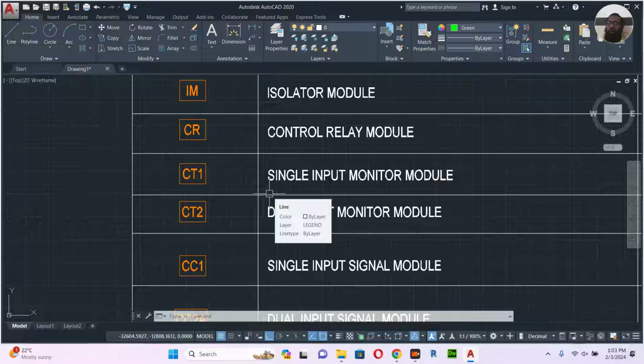So let's say one AC broke. What will happen? The device will break, or maybe there's a possibility of fire because it's working with batteries and many other items. So the AC has to be monitored every time to see whether it is working or not. In case the AC is switched off or any accident happens, this monitor module gives a signal to the fire alarm. It will trigger the sounder. So a sound will come, and the people working in the building, the guard room, or a certain person will understand there is a problem. Then they will come and fix it before any disaster happens.